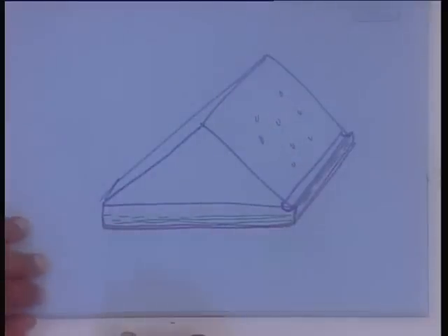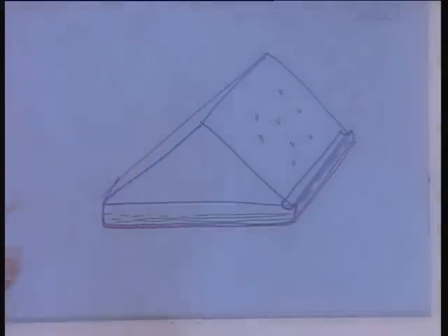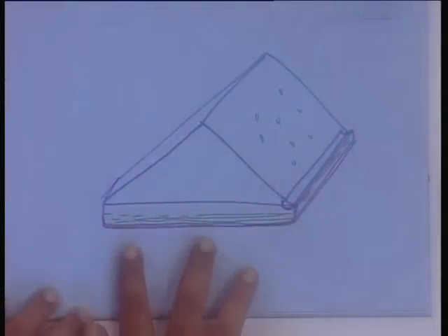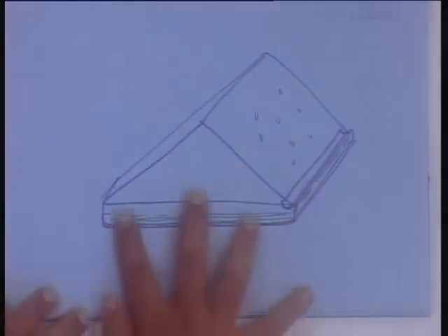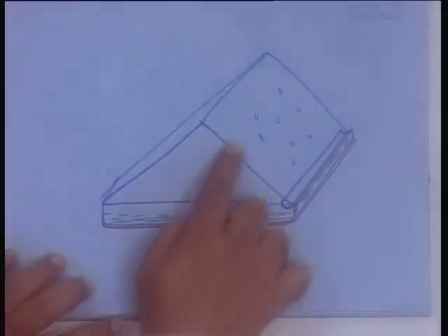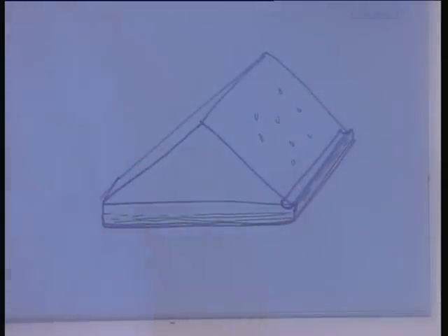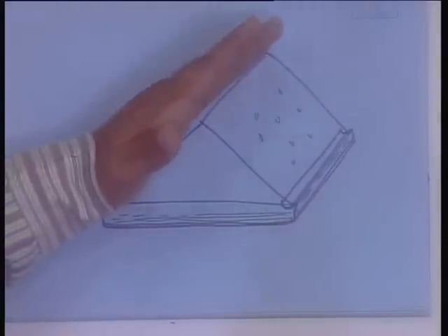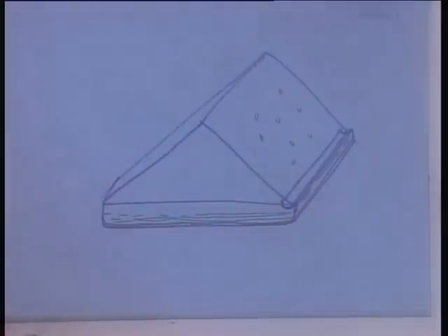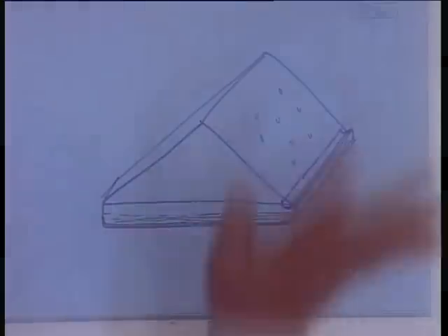The reason is that you might imagine the whole thing as an electrical circuit, some energy coming in like a battery, and there are resistances. Because the heat that is absorbed goes up, the fluid is evaporated, and that reaches there. In between, the fluid experiences some resistance. So, there is a temperature here, there is a temperature here. The temperatures can be imagined as similar to voltages. So, if you bring down this voltage, there is a finite resistance in between. So, it will result in the reduction of this voltage also, that means this temperature also. So, it does not really increase the yield. So, simply leave it as it is, it works.